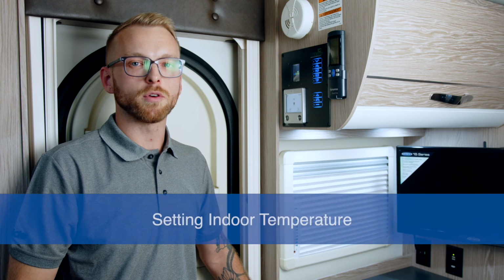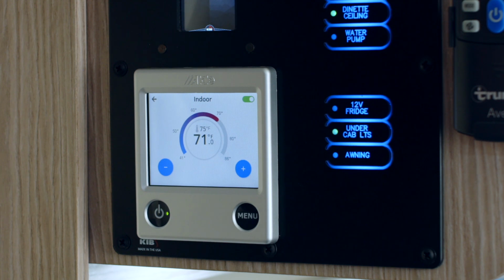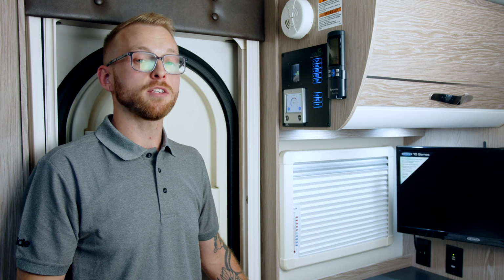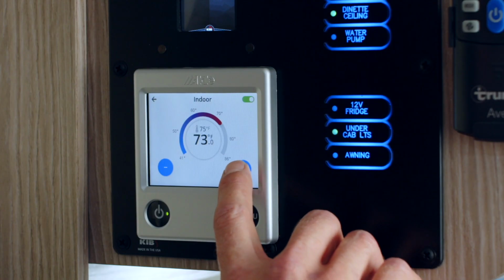The status screen of your Alde 3030 control panel shows the current temperature inside of your RV. On the screen, you will see two temperature readouts. The smaller number at the top is the temperature that is currently inside of the RV. The larger number at the bottom is the set point of the Alde control panel. To change this set point, you will use either the plus or minus icons on either side of the screen.